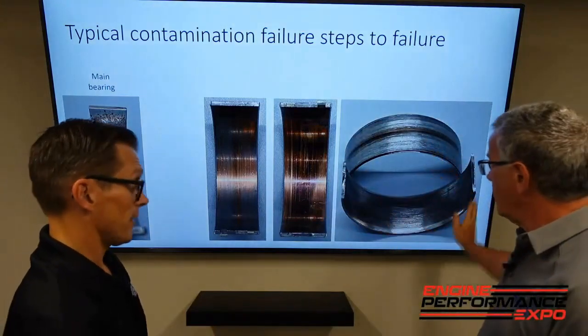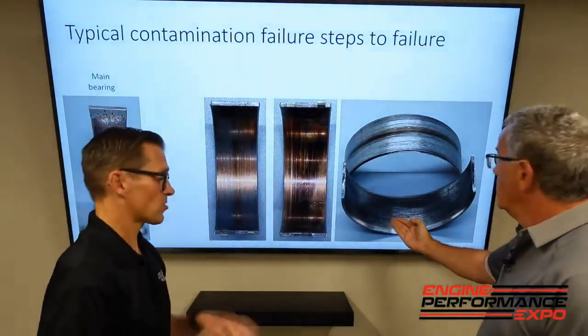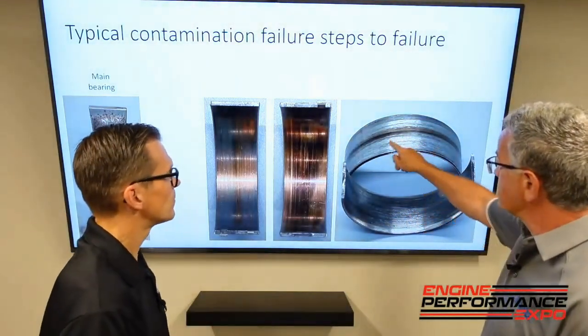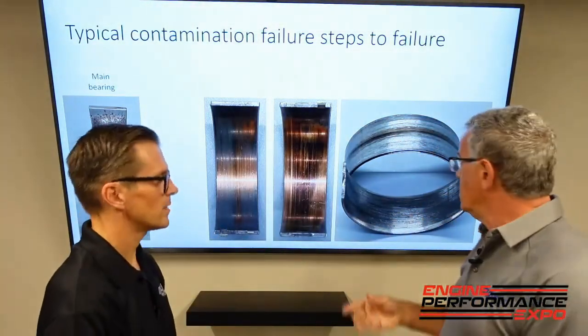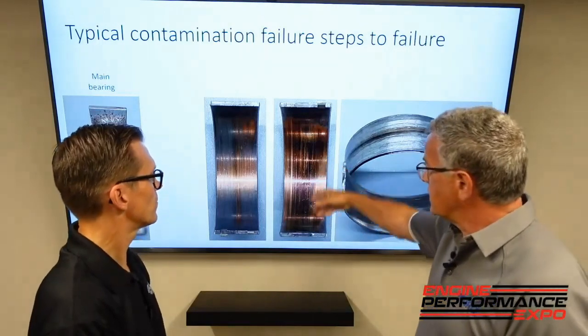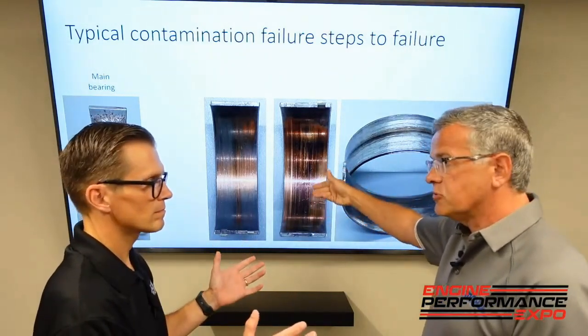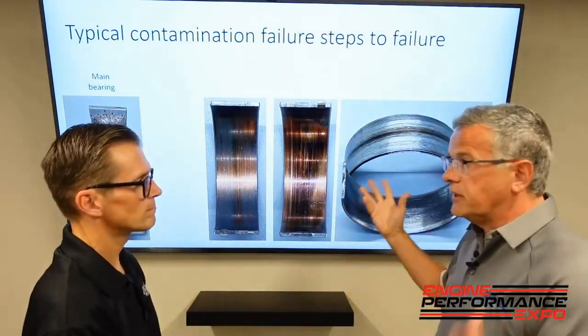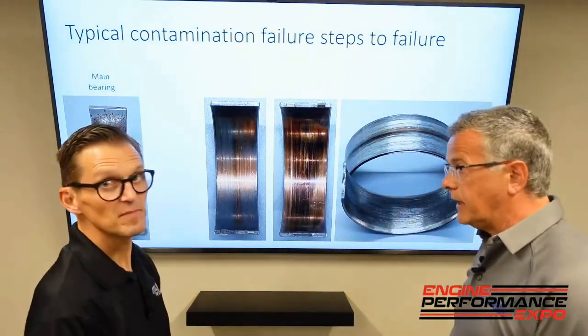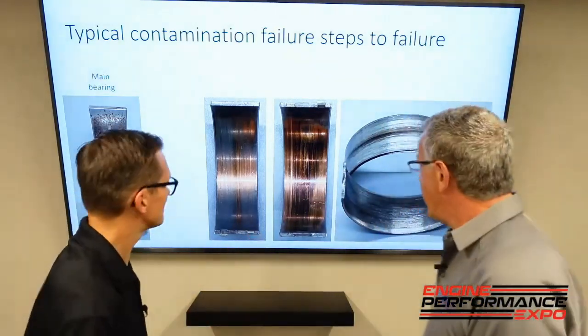Now we've completely lost the substrate. Yeah, it's totally wiped out. The bearing spun, you can see by the outside, the bearing spun around. Simply the fact that it lost so much oil clearance, the frictional temperature got hot. The bearing said, I'm grabbing onto you and I'm going around. And she's done. That's it. Yeah, bad day.